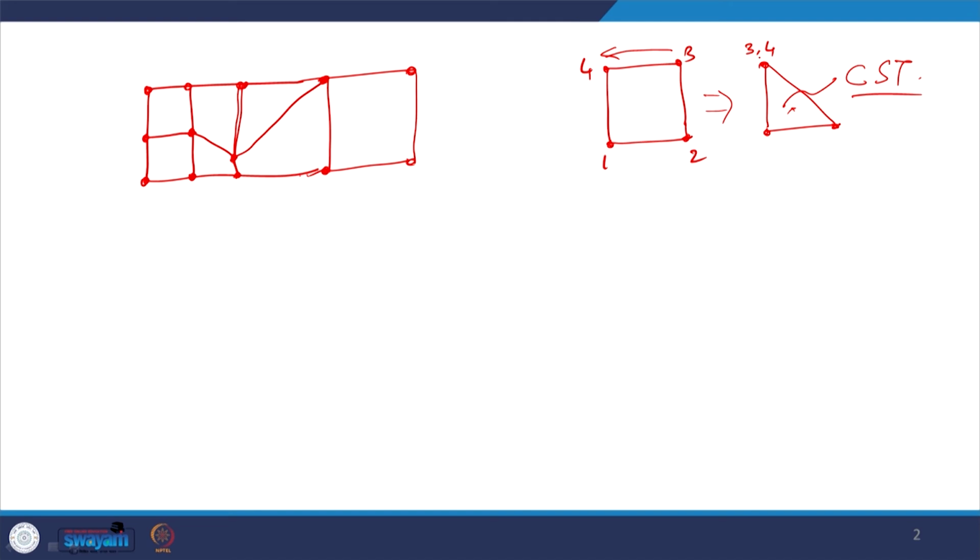Any computation around this location is questionable, but fortunately we can operate at the centroid, because all the strain fields are constants. So, we do not really need to evaluate it at that point of singularity, and things are under control. New finite elements can be developed this way, and this process is called the process of degeneration.